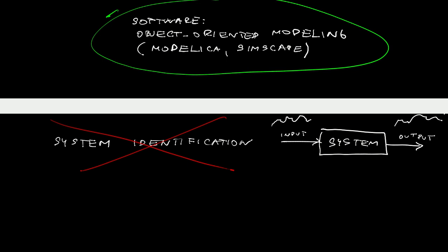So again, some data. And then system identification provides you with tools how to use these input and output data to get a mathematical model. Not only the coefficients, but also perhaps the structure of the model, order, whether it must be linear, nonlinear, time varying, whatsoever.